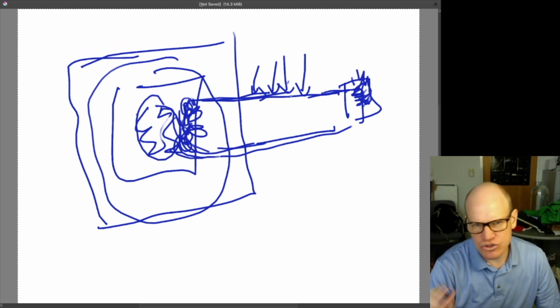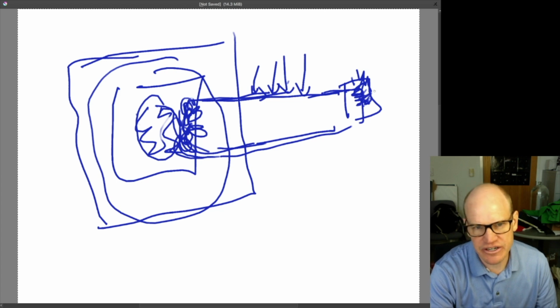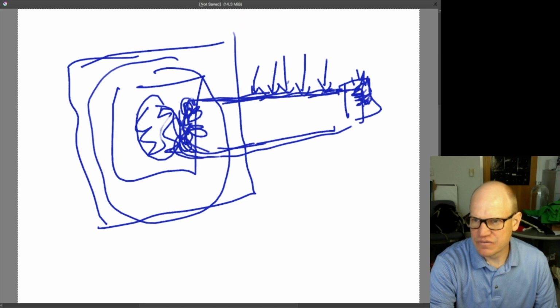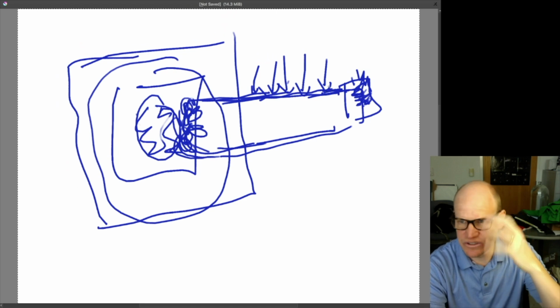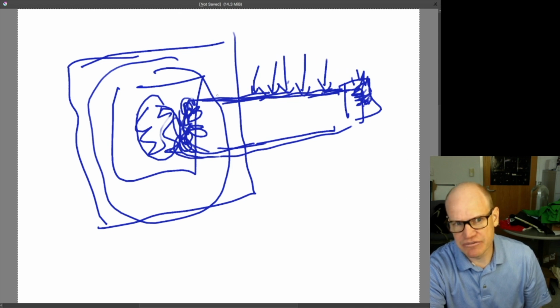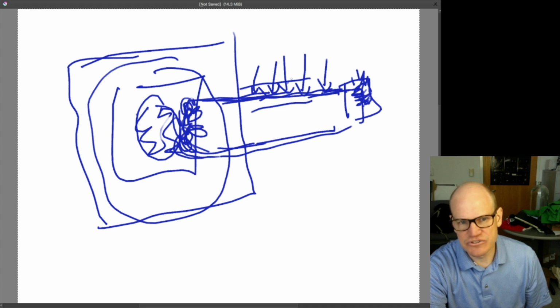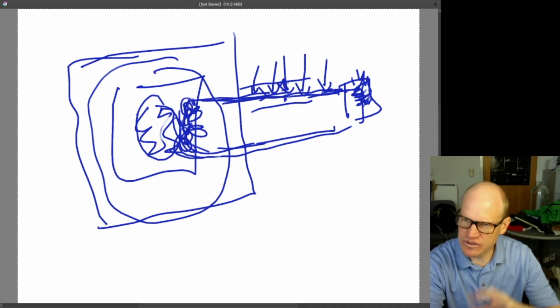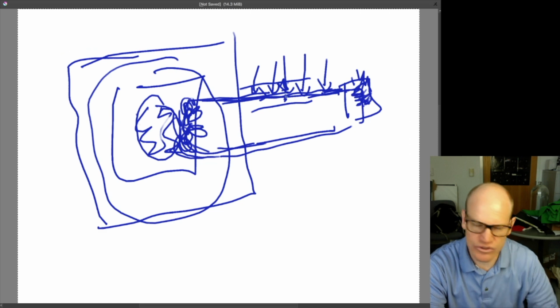So it will cool down quickly unless it's insulated, right? This can be underground. So you can run these pipes underground, and the thermal conductivity of soil is tiny. You could have it insulated, right? You could have it running underground with a layer of air around it, so that you get even less thermal conductivity. So there are ways to engineer it so that things stay hot over long distances.